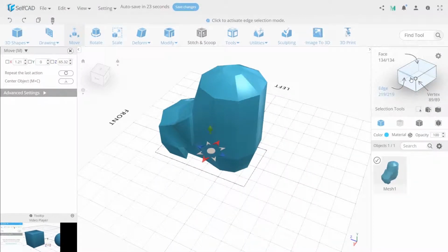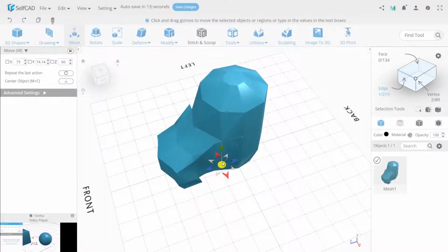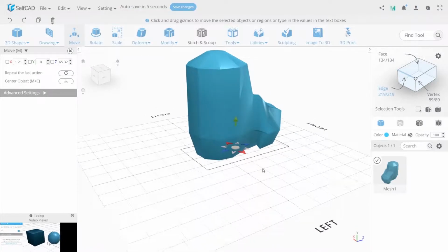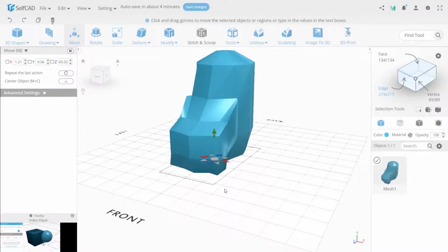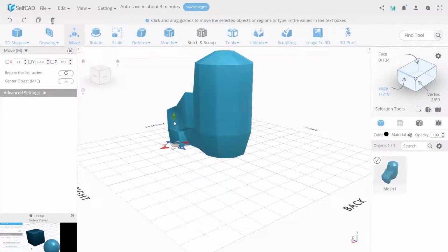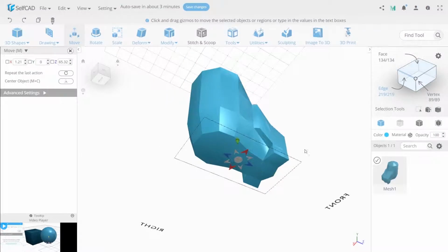Also select polygons near the leg corner and move them so they can look like a part of the body. Also repeat your moves on another side. And also select the edges of the bottom of the legs and move them a little bit upper, on 0 by Y-axis.